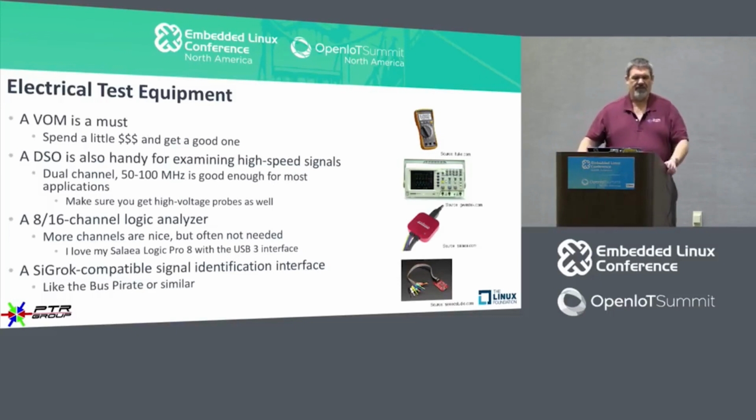Now, another thing that's handy is a Sigrok compatible signal identification interface, AKA Bus Pirate or something similar. We'll use these as a way of just being able to identify the type of signal that it is. Is it a JTAG? Is it a serial port? Is it an I2C? What is it? Because if you start plugging things in without really knowing what it is, you'll likely let the magic blue smoke escape, and that's bad. Not to mention they come in and go, what does that smell? No, I took a shower. It's not me. It's that thing.